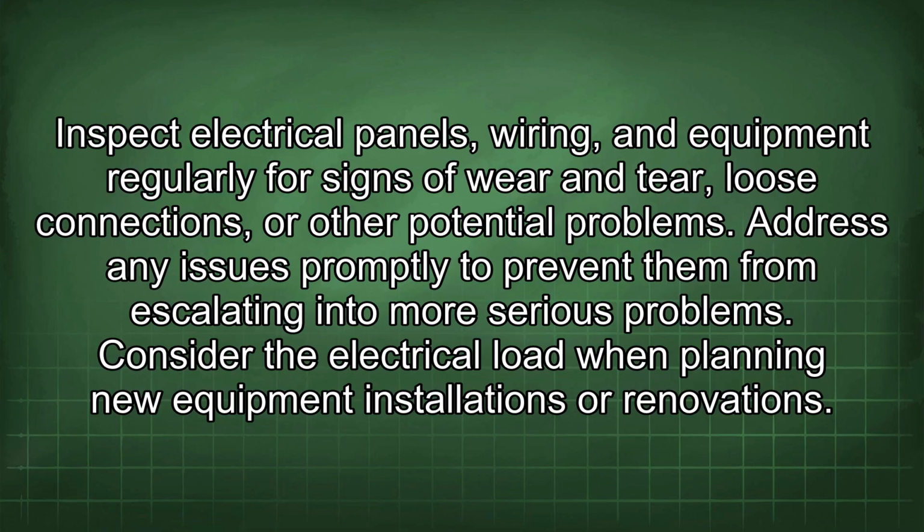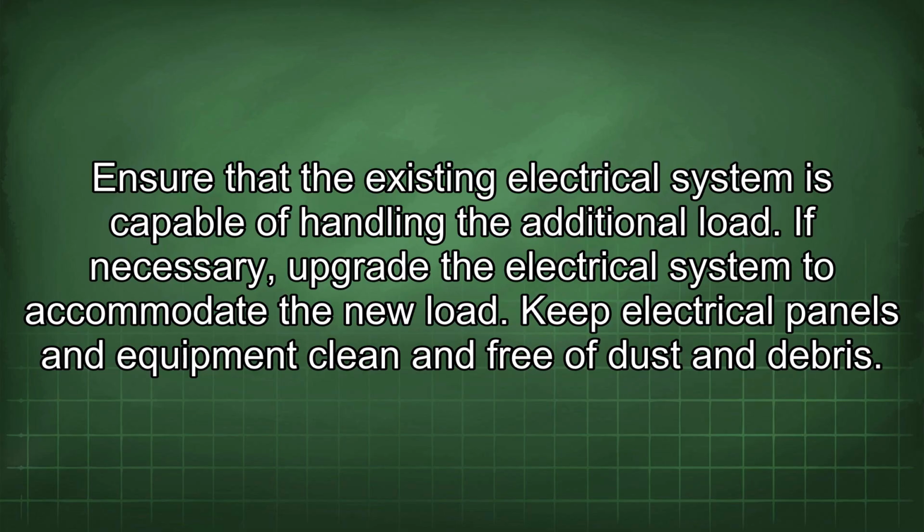Consider the electrical load when planning new equipment installations or renovations. Ensure that the existing electrical system is capable of handling the additional load. If necessary, upgrade the electrical system to accommodate the new load. Keep electrical panels and equipment clean and free of dust and debris.